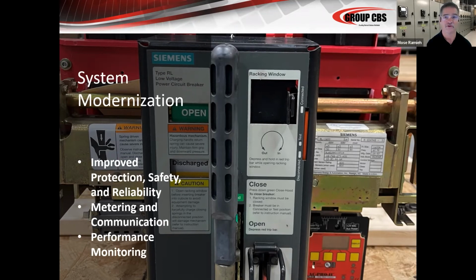Okay, just opening that breaker and closing that breaker is great maintenance, right? Just cycling these devices, because once again, if they sit there closed for years and years and years, and you expect that mechanism to work properly, with all the rollers and the lubrication, and that's a whole other presentation, really. But once again, just opening and closing them, that's maintenance, even if you can't take a longer window, or maybe you don't have time to primary inject this breaker, but you have time to secondary inject it. So what activity can you implement?